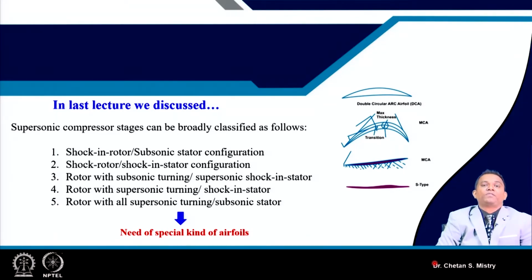Similarly, for the leading edge of transonic aerofoils, if we make it sharper, it will act well when working under one flow condition. We know our compressor mostly works under off-design condition. Whether commercial aircraft or military aircraft, for both configurations, most of the time the compressor works under off-design condition.